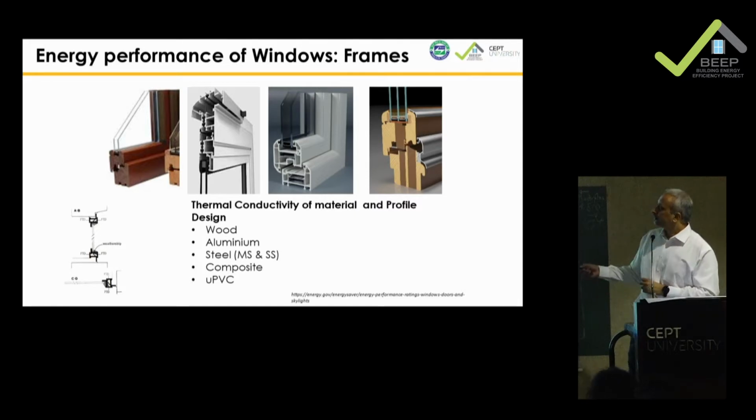So what they are trying to do is find a way by which you can supplement what glass is doing. Okay, you have double glazed glass, and if there's a gasket here, you will try to make a lighter frame without much thermal bridging or thermal breaking. At the same time, you need to maintain the structural strength of the material as well. So sometimes you see some metal inserts in the UPVC frames. This guy is trying to avoid all thermal breaks. Although it's aluminum, inside he has filled it up with wood so that it doesn't become a thermal bridge.